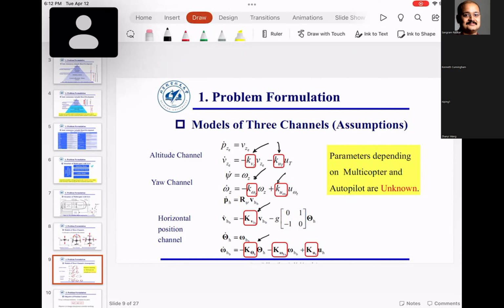What that means is, if the data coming from the sensor is at 50 hertz, but the autopilot is running at 100 hertz, then you want to interpolate the incoming data in such a way that you have an approximate value in between those 2 data points. So even though your sensor values are coming to you at 50 hertz, you design some kind of an interpolation algorithm and get that data converted into 100 hertz.